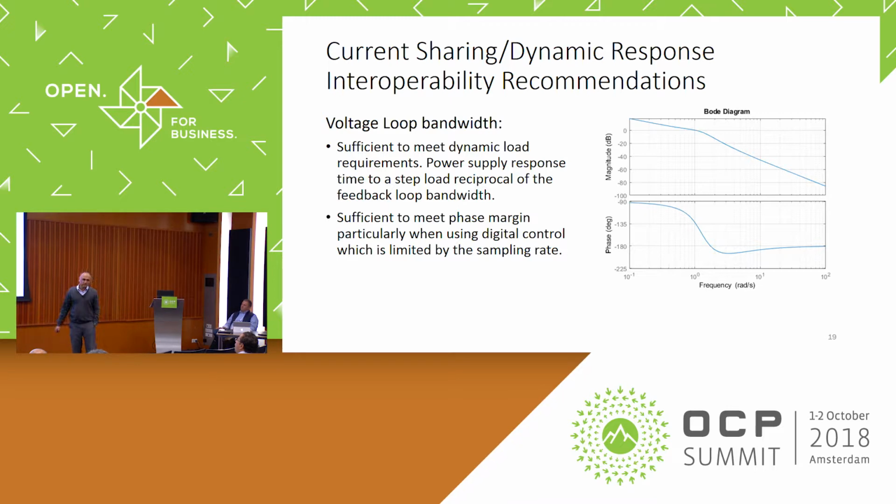And again, just re-emphasizing what I just said, this is the 101 of the feedback loop stability criteria, that the voltage loop bandwidth should be sufficient to meet the dynamic load response and sufficient phase margin so that things settle down in a proper fashion.